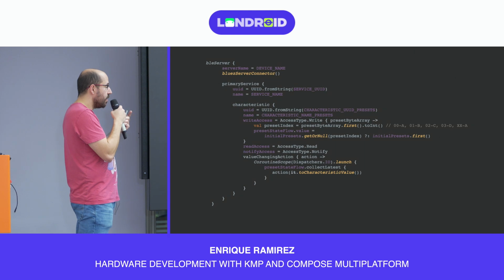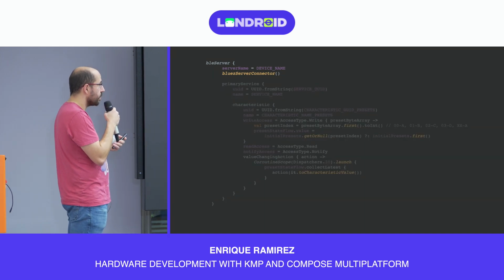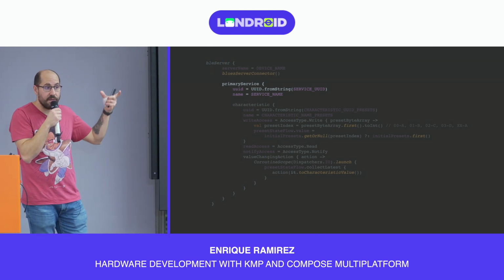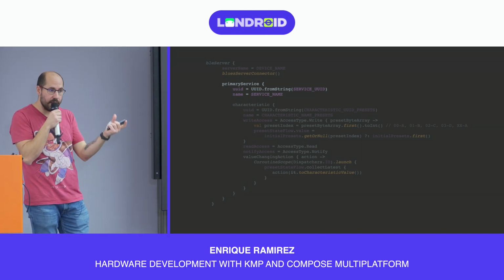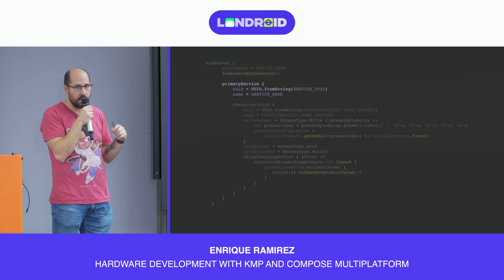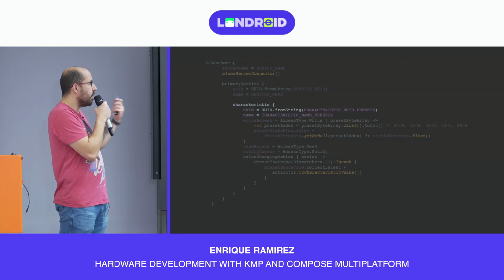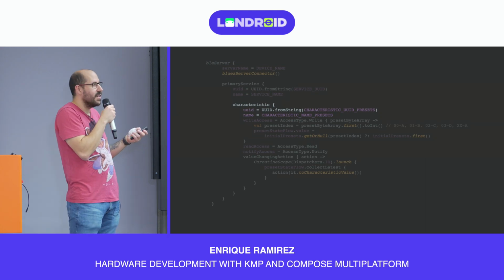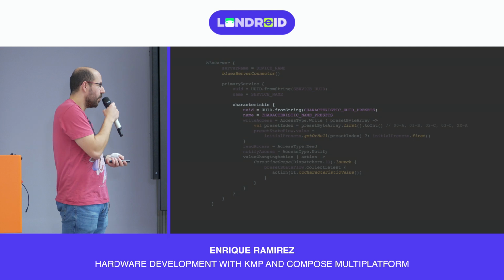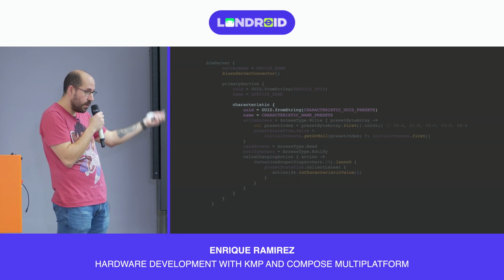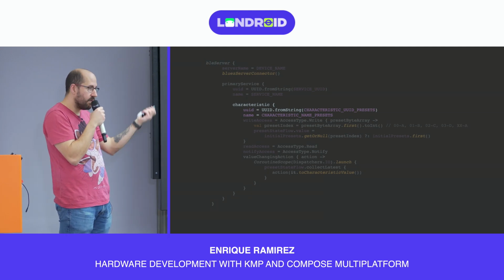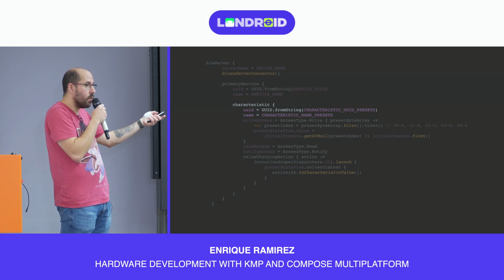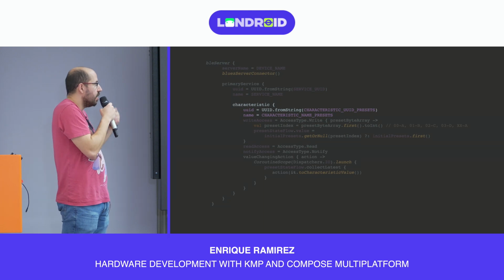Let me explain. You need to define a service, which means you need to give it a UUID, an identifier for your service. So when you create your client application, you can identify it easily without having to search or anything. The characteristics will be the equivalent of endpoints in REST, if you want, but you also have to give them UUIDs for the same reason. You can find them, but they are like ports that you can read, write, or get notifications from, or subscribe to. So that's how you do it.